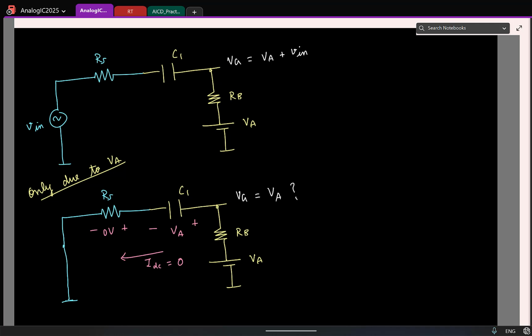Again, remember that, see, what is the voltage current relation for a capacitor? I mean voltage current, not Q. What is the voltage of the capacitor? 1 by C integral of i dt. Fine. Now, if let us say a DC current flows through the capacitor, which means this current is constant, so what will happen to the voltage? It will eventually keep increasing. So as long as the voltages in your circuit are all finite, in steady state, the DC current flowing through a capacitor is always 0.